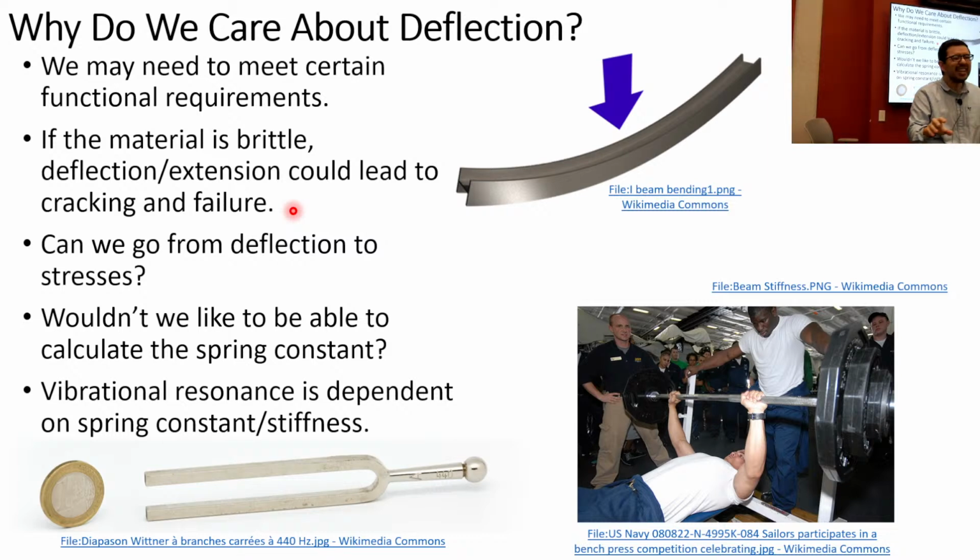So why would it be wishy-washy? Why would it be really easy to push around inside the washing machine cavity? Any ideas? Yes? Damping. Well, is that damping? There is damping involved, yes, but I could have very high stiffness and still have damping, right? My point is that it's not very stiff.